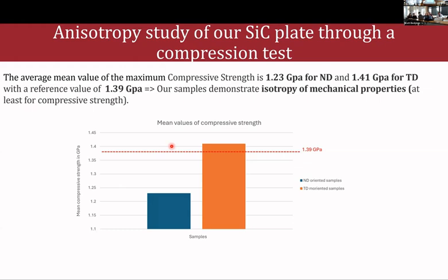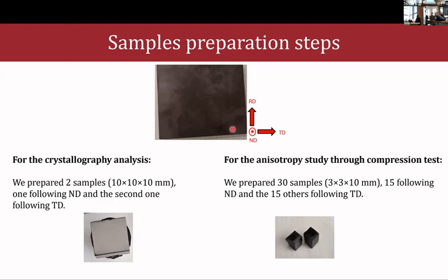Yeah, we had that problem. For example, with the transverse oriented sample, we had that problem because to get the normal samples, at the shop they were just cutting it, they placed the plate this way and we were done. But for the transverse direction samples, they were obliged to turn the plate this way and cut it through. So the surfaces were not all flat. You have to spend a lot of time getting that right.